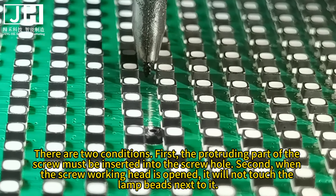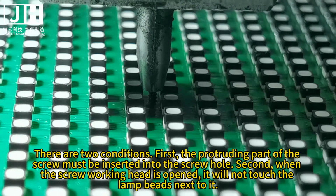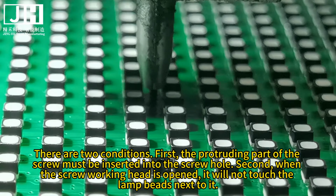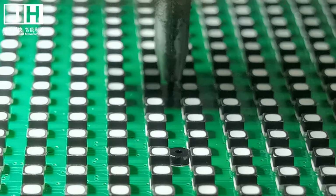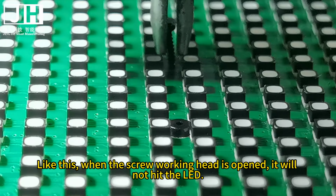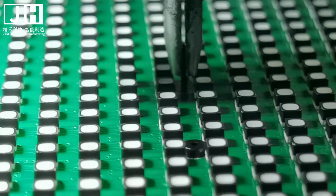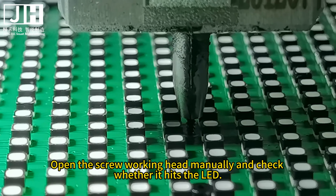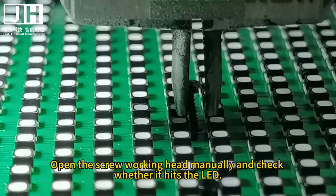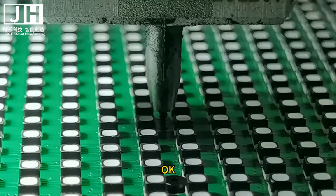There are two conditions. First, the protruding part of the screw must be inserted into the screw hole. Second, when the screw working head is opened, it will not touch the lamp beads next to it. Like this, when the screw working head is opened, it will not hit the LED. Open the screw working head manually and check whether it hits the LED. OK.